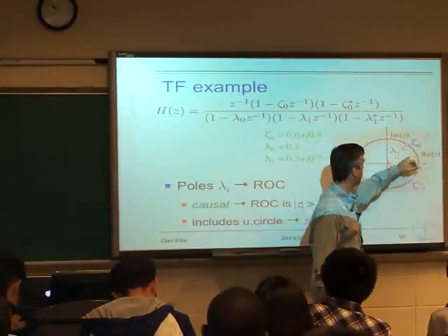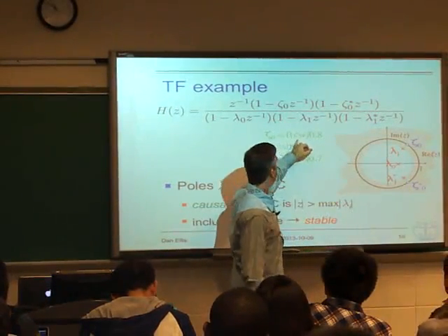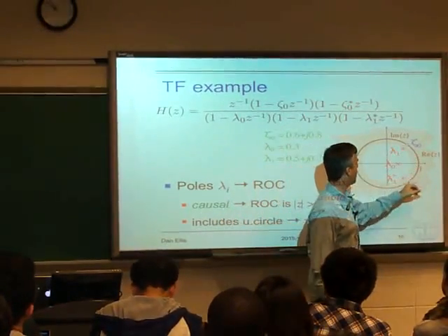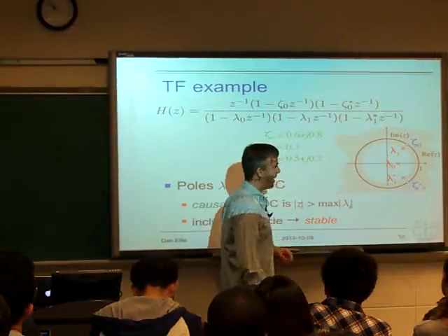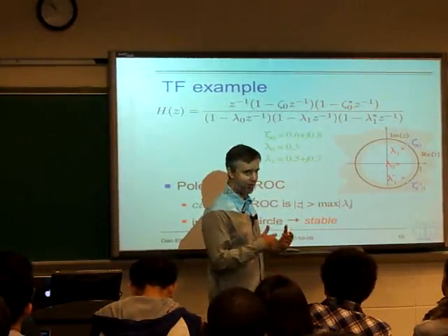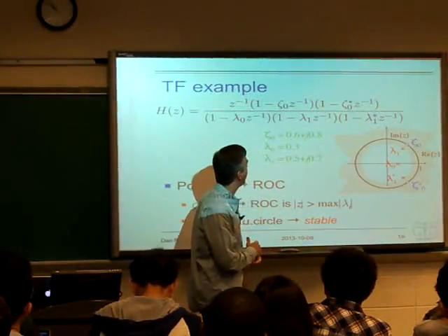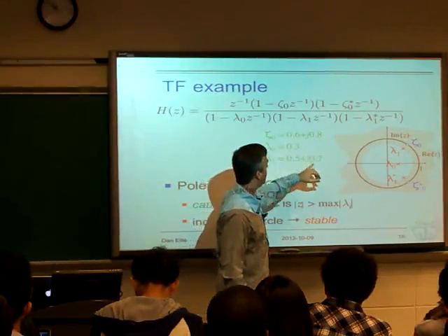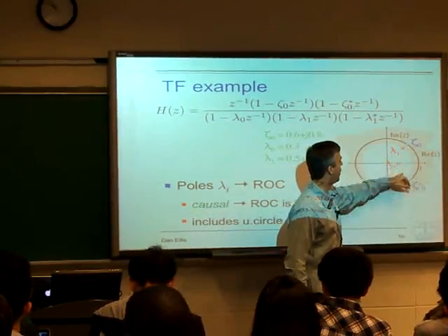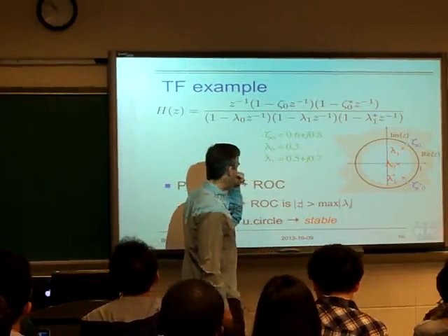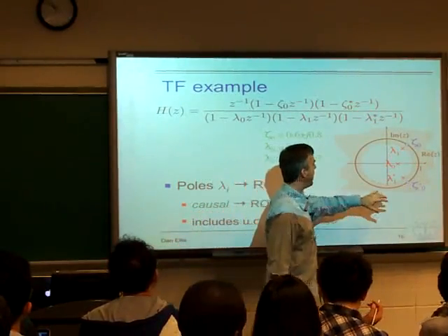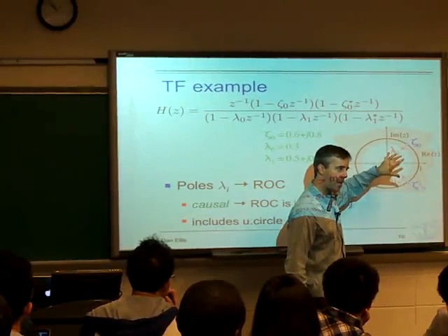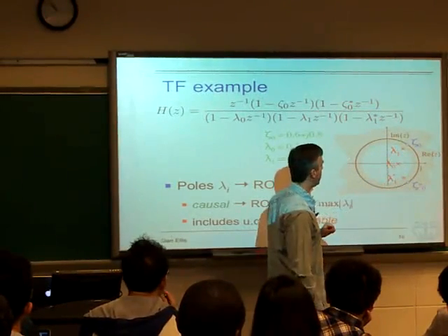So here are two zeros, and it turns out that this is part of a 3, 4, 5 triangle. So these two zeros are on the unit circle. Again, that doesn't happen in real life, but happens in examples in textbooks. And so here are three poles, the one real pole and the conjugate pole pair. This pole-zero diagram describes the closed form expression for the z-transform.